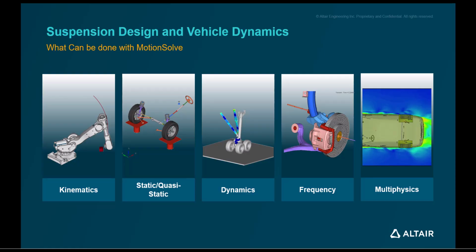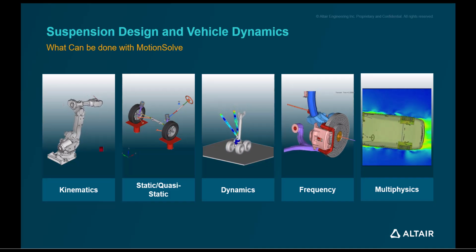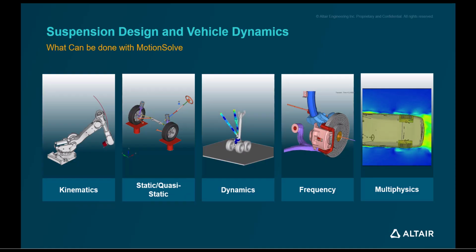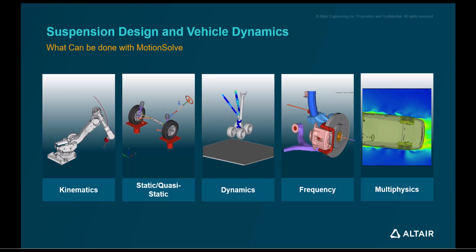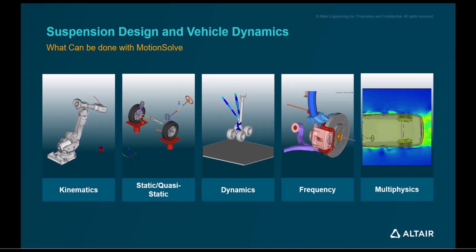Areas that we specialize in: kinematics, so studying the motion of an end effector; static and quasi-static simulation to study the compliance of a suspension system; dynamics, studying the load on an aircraft landing gear; frequency, where we can extract loads for durability analysis or study low frequency for NVH. And then multiphysics, where we can perform multidisciplinary analysis with a couple of other products like controls, CFD, and bulk particle data material.